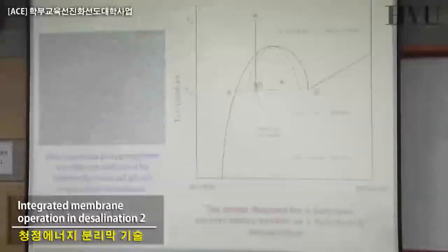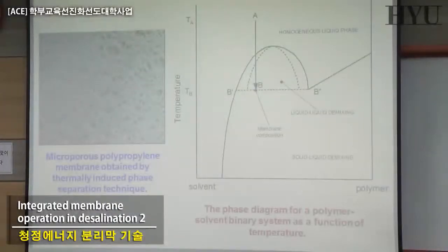So you have to produce a very high transmembrane flux. For doing this, we need a level of porosity higher than 70–80%. Otherwise, you lose the competition. At this level of porosity, producing large-scale membranes, some people are talking about 85, would be very nice.